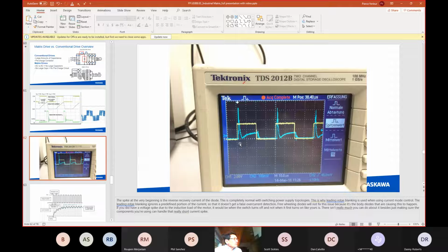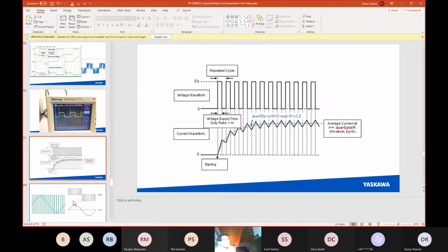But you can see on this scope the rise time, and then you see this thing going on here. What's that? Well, the inductor doesn't immediately react when the voltage shuts off. Remember, it's a current shock absorber, so it's going to ramp down again the same way that it ramped up. This portion here is due to the inductive reactance in the motor. This is due to the flyback diode in the circuitry of the H-bridge. So here is what I'm talking about.